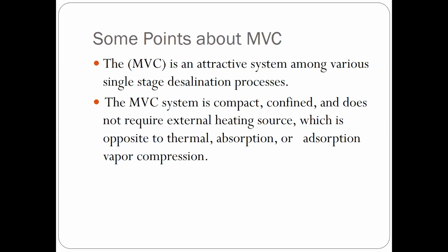Or it might not be electric power, because here, as it appears from the title, it's a mechanical vapor compression unit. So we're talking about a compressor which runs mechanically. So what you need is just mechanical power input. The mechanical power input can be given by electricity, for example. You can have a compressor that runs with electric power, or you can have the compressor connected to a diesel engine if you are talking about a remote area where no grid is there. So a diesel engine can operate the unit and then you have your desalination system operating.